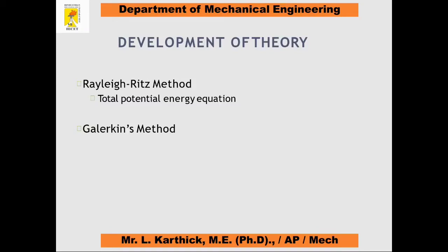The next one is the Galerkin method. Here also we find the same thing, but the Galerkin method is defined for non-linear problems and complicated or complex structural problems. Linear problems are handled and carried out by the Rayleigh-Ritz method, while non-linear, non-structural, complex and complicated problems are handled by the Galerkin approach.